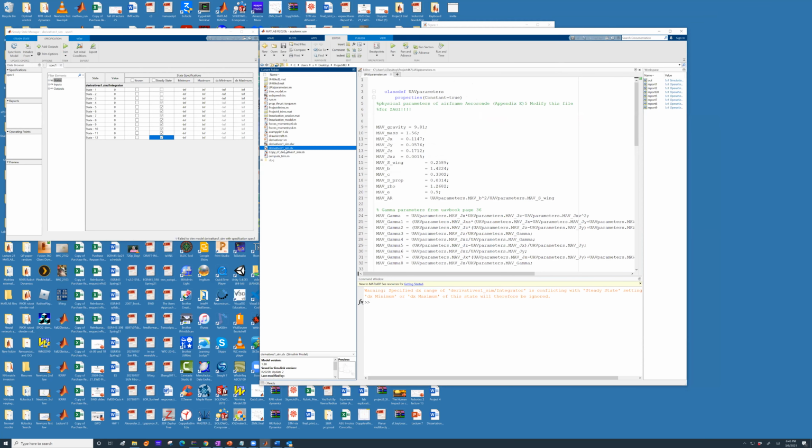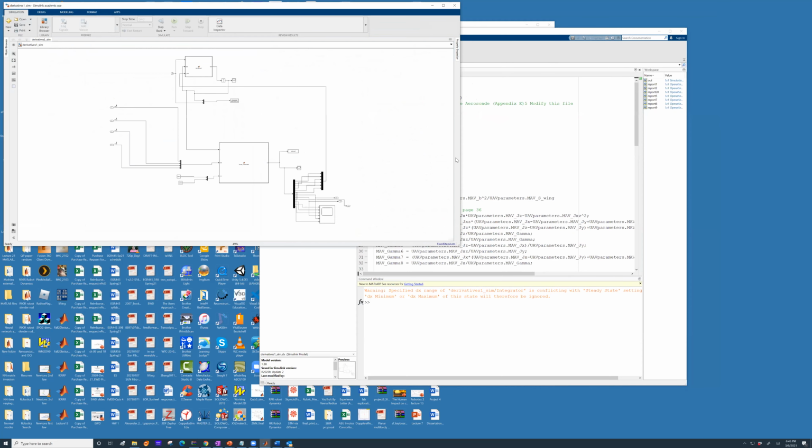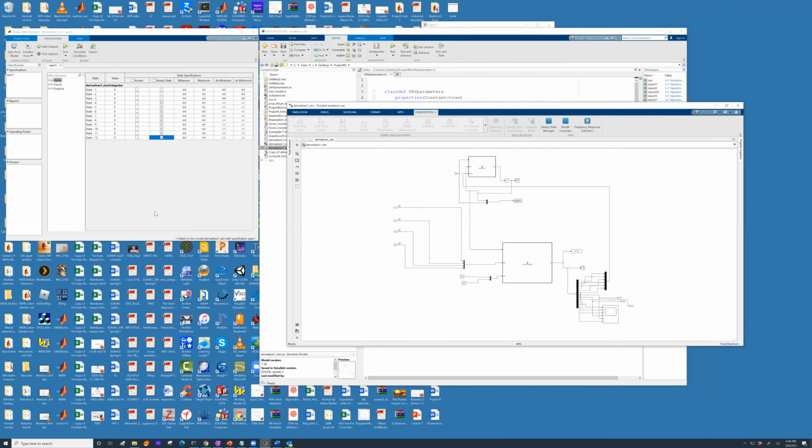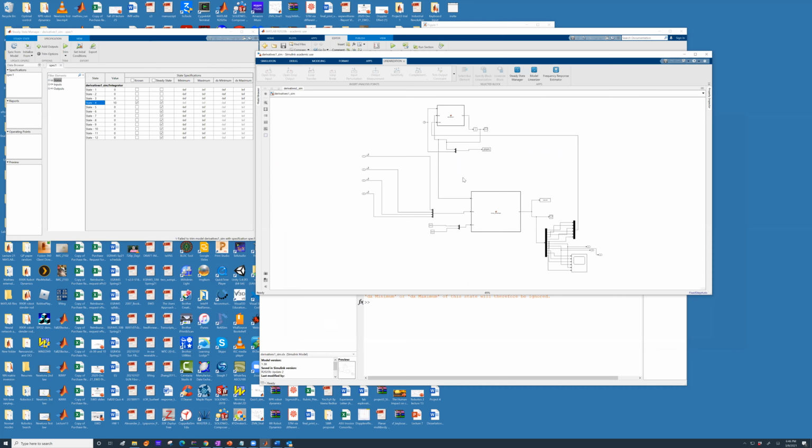Derivatives 1 SLX. So I got an error in this file. Now what I'm going to do is add one more constraint. I'm going to say that my airspeed VA has a constant value, and that is known. So I'm going to add 10 to the airspeed, because I want it to be constant. And honestly, other parameters at this point, I really don't care.